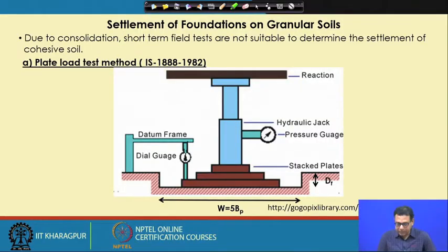So, what is the plate load test? Instead of using the real foundation, we are using a plate on which we are applying the load, and then we are measuring the settlement. So, this plate is treated as a foundation, and ideally the depth at which we are placing this plate should be equal to the depth of the foundation. But sometimes it may not be possible. So, in that case, when you use this data, we have to take proper precaution, or you have to apply the depth corrections.